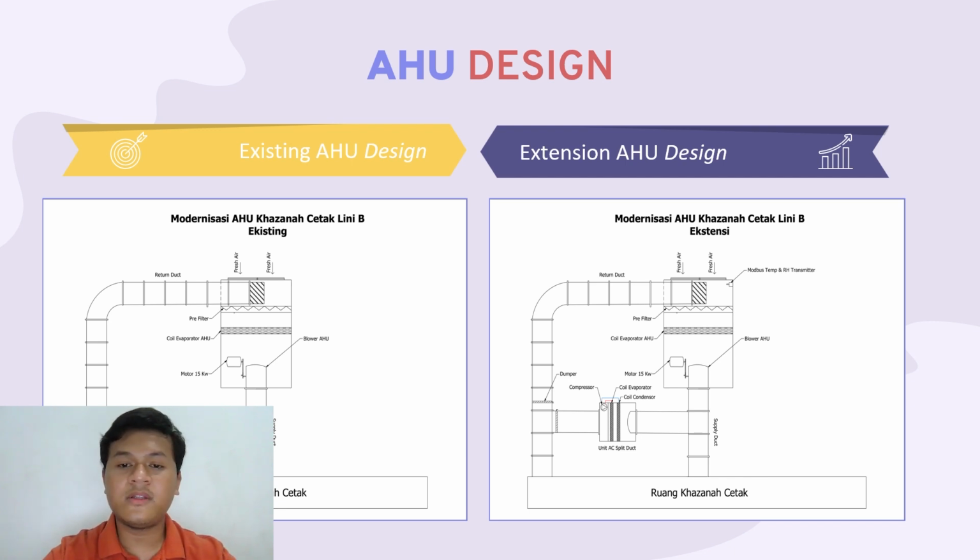As you can see on the extension AHU design, there is an added AC split duct unit. Both are controlled by a multi-channel input and output PLC. As a result, the AHU return air mixes with outside air, increasing the relative humidity measurement.